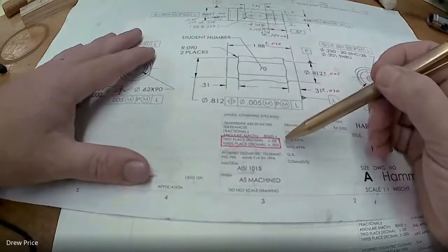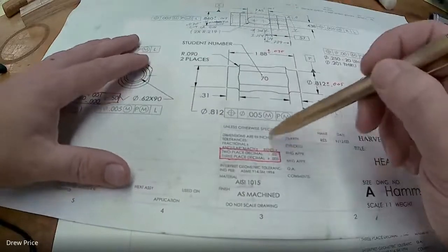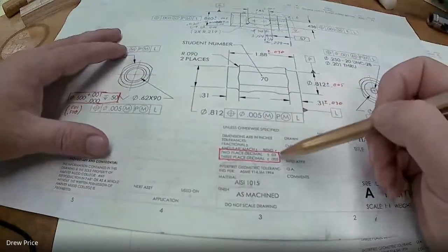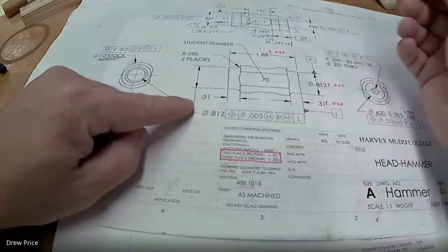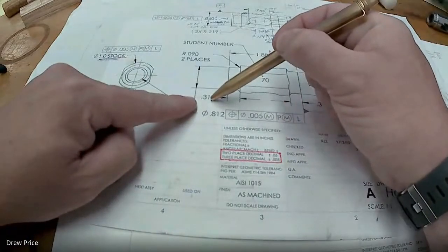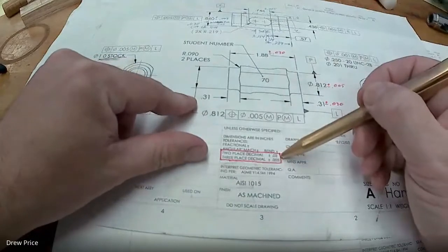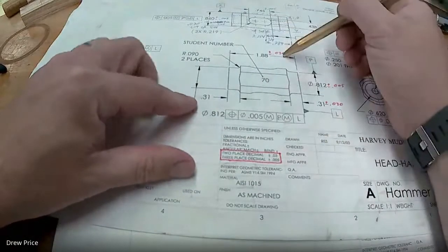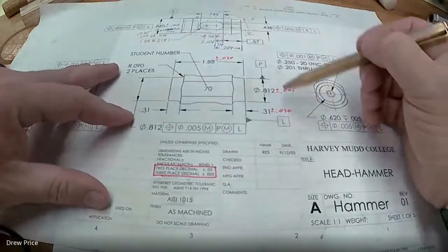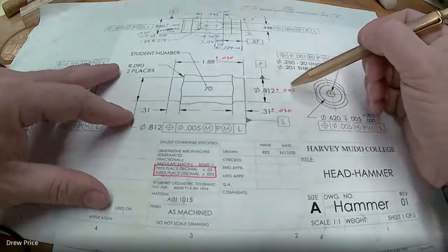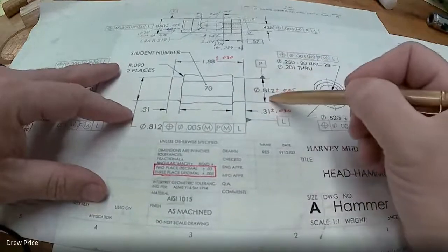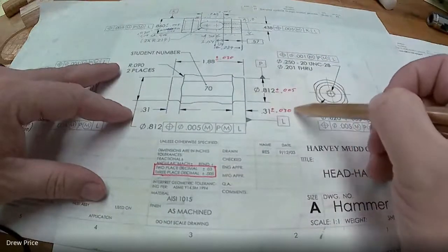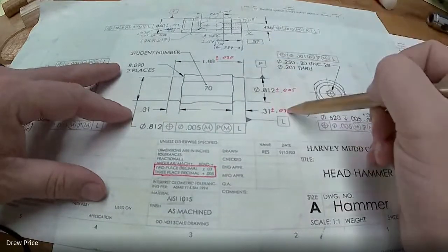Other places on drawings you'll see where there's not an explicit dimension printed on the drawing. That's something that you would reference in the tolerance block at the bottom of the drawing, which gives the implied tolerances. For example, these 2-digit numbers have a tolerance in the tolerance block of plus or minus 30 thousandths of an inch. So on this drawing, I've marked in what those actually translate to that are given down here, because this is a drawing that I would use in the shop, and I want to easily be able to remind myself which one I have to pay attention to.